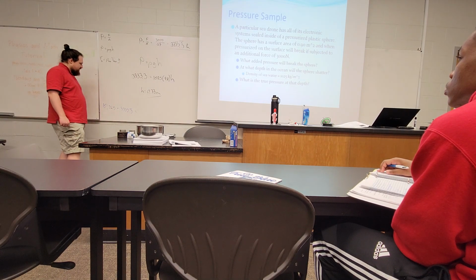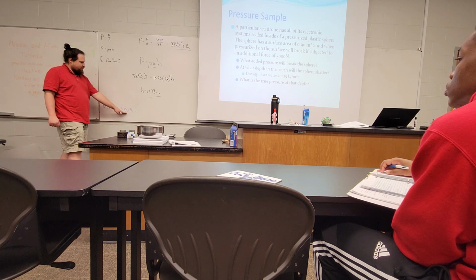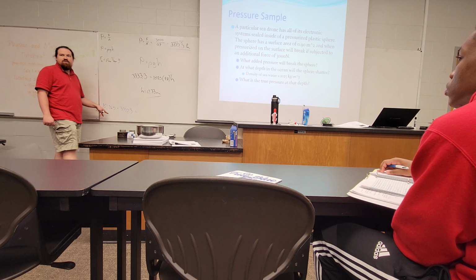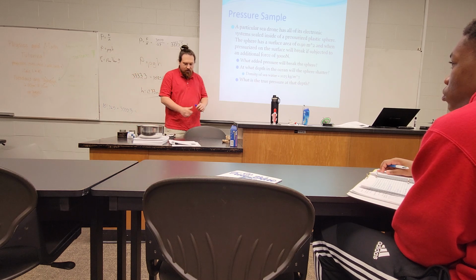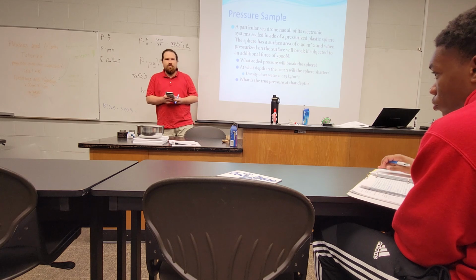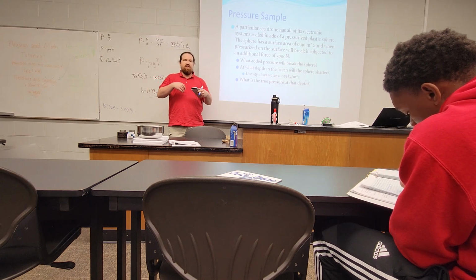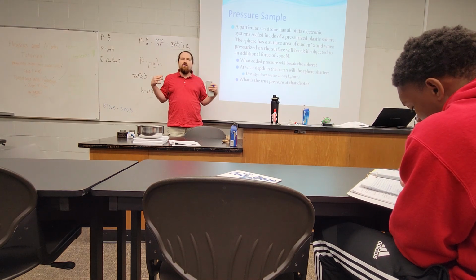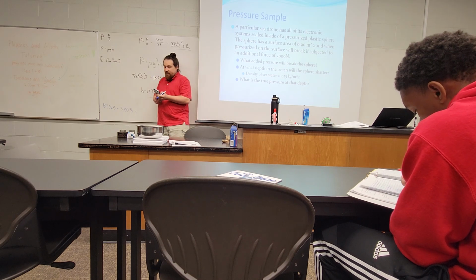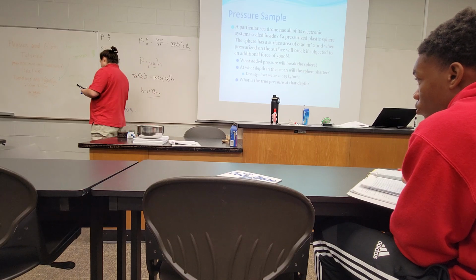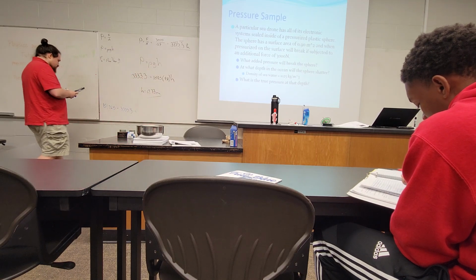Whenever the homework mentions true pressure, that's basically just the pressure added from the fluid plus whatever the atmospheric pressure is above that. So true pressure is simply referring to the real total. Most things on the surface are built and grown such that atmospheric pressure doesn't bother us. We're equalized for it, so it doesn't especially matter, but for some instrumentation you do have to know what the true pressure is.